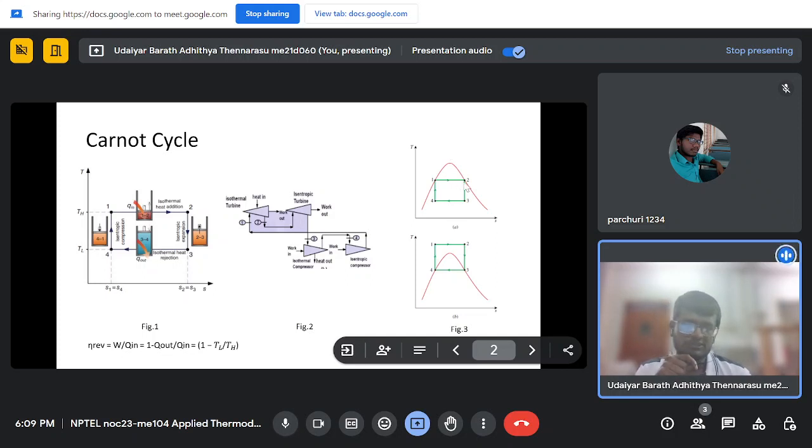And the second is the two-phase expansion and compression process. Two-phase expansion, though the turbines may be efficient, will create troubles: the liquid will generally go and impinge on the turbine blades, and it can erode the turbines.